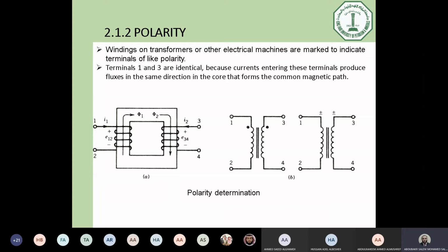For all transformers, because the transformers are already wound and you are using them without any winding, you have to use a ready transformer. So it's already wound, and there is an internal sign to know the direction of winding. However, you cannot have access to the core from inside the transformer. So we have to make something to understand or know the flux direction.